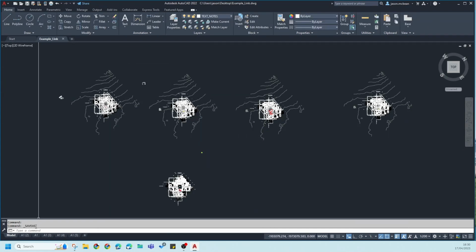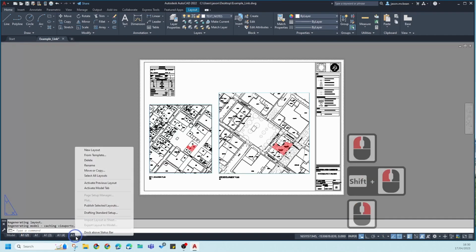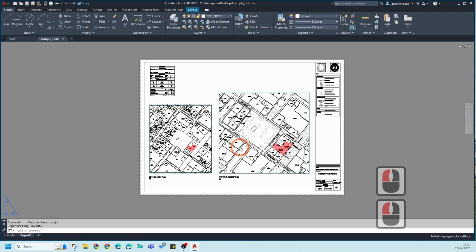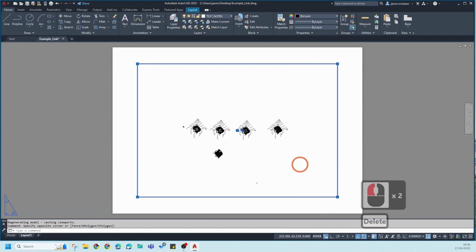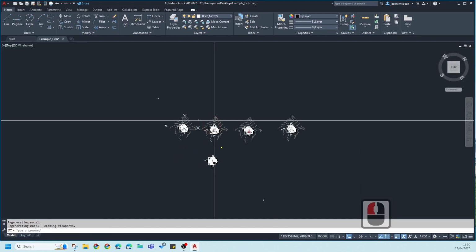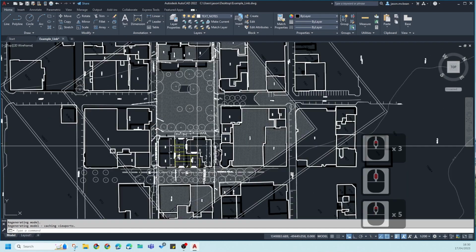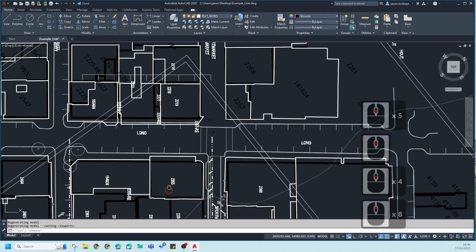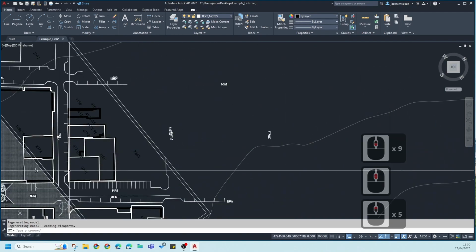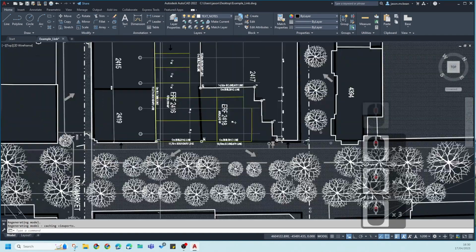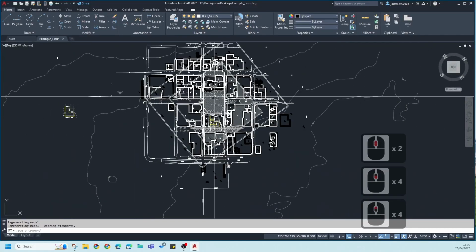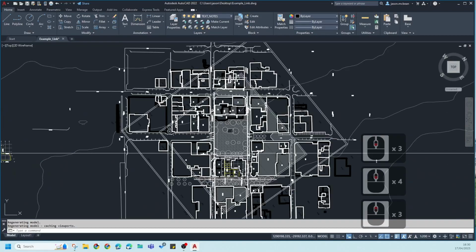The next thing you're going to do is delete all the sheets in the project. So select and delete all of the sheets that you don't need. You can delete the viewport and the view that remains, because this is purely going to be a drawing that we're going to link to Revit. Then select the appropriate plan that you're going to link. Wherever your site plan was, you can either use your planting plan or you can use your site plan. In this example, it doesn't really matter. I'm going to use this plan as an example.